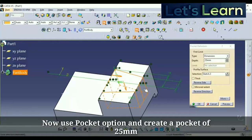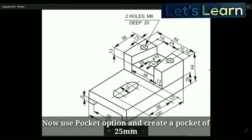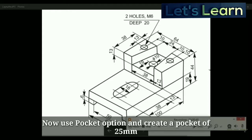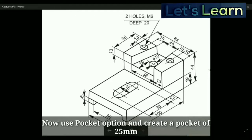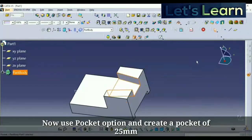Give the distance to that dimension, limit or dimension, we can say. So it's 13. You can see the whole pocket is up to 13 mm. Then just give it 13 and click OK.